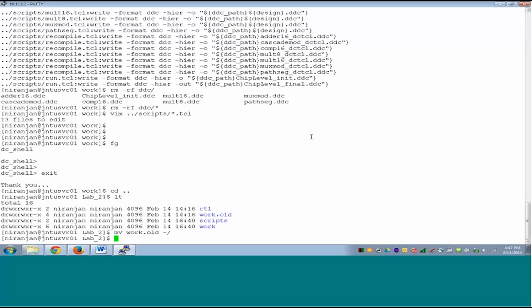This lab has multiple skills that are being used, so it shows a good usage of source .synopsys_dc.setup. Although the methodology is slightly old, it still gives us a good insight into how to build our scripts and what to check, how to make sure that design netlists are written at a particular place, and how to arrange our directory structure and so on. Let me discuss some summary about the design itself.